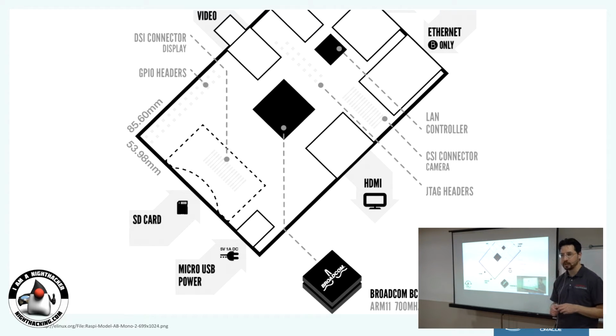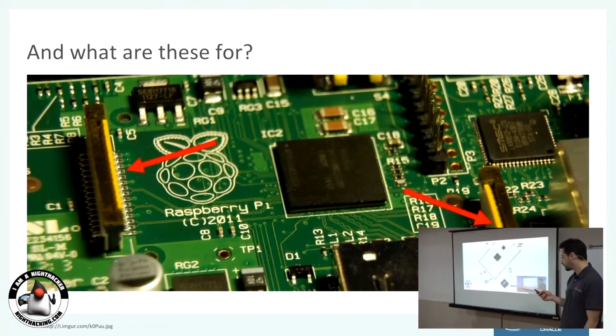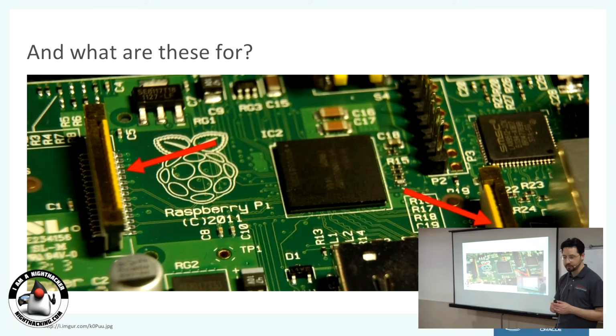So it's a really nice platform for building small embedded hardware, and it runs on very low power. You can power it over micro USB, with less than 1 amp, sometimes down to 300 to 500 milliamps. And you can power it off a battery as well, so that device is running off a little battery inside of it. So it's a good platform for prototyping.